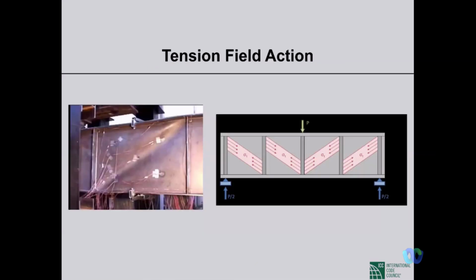Now, one more interesting thing. This is so interesting. When we talk about tension, we talk about shear lag factor. When we talk about compression, we talk about flexural buckling. When we talk about shear, we talk about tension field action. This is the peculiarity of steel structures design.